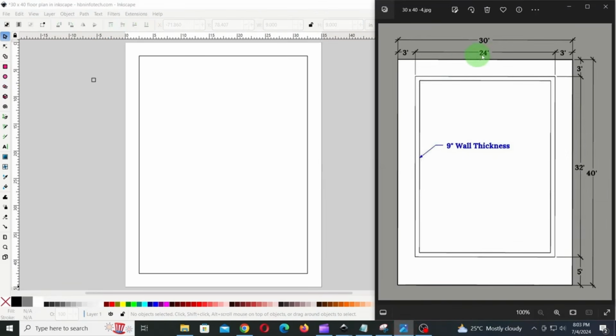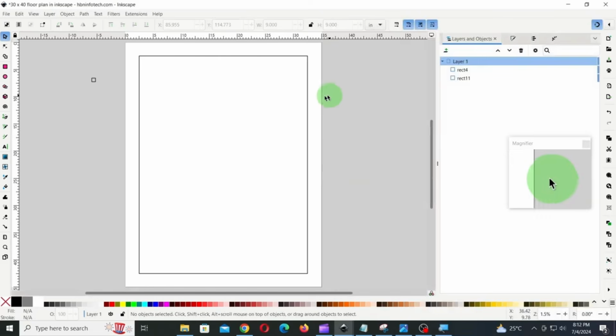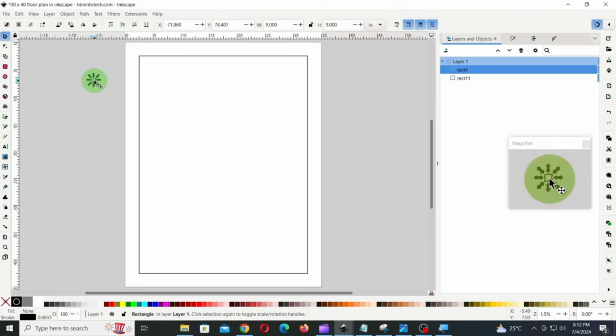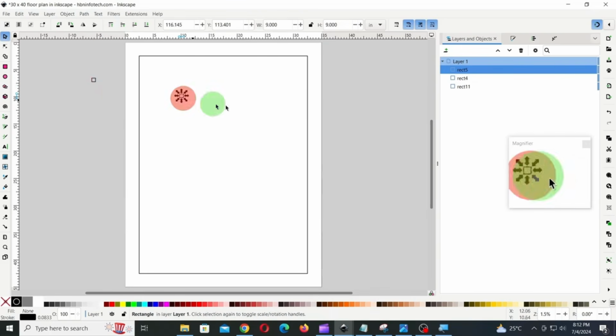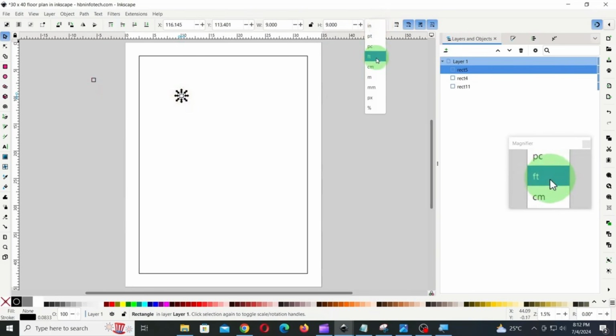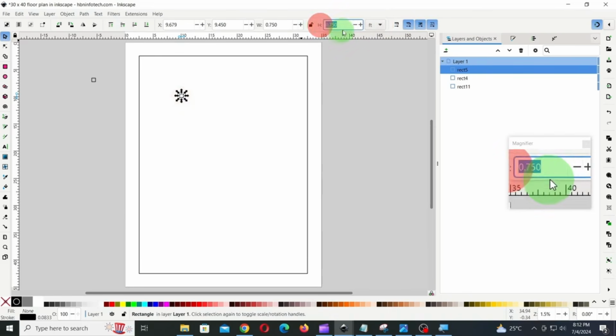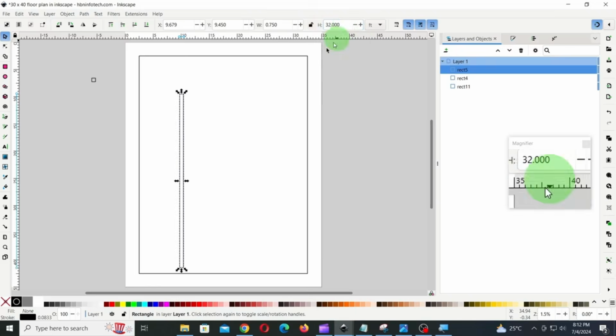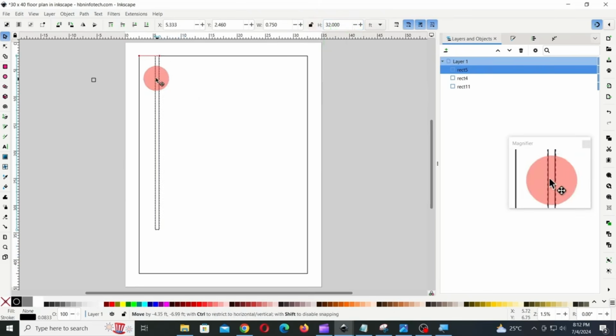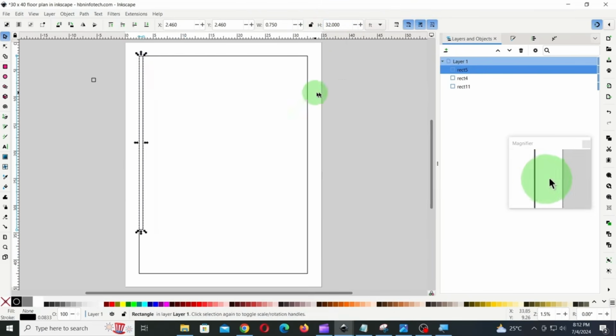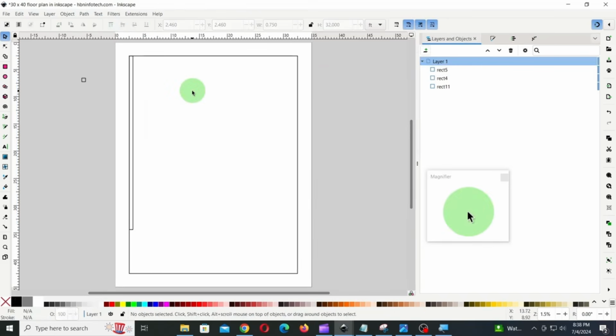The outer wall that we are going to create is 24 feet by 32 feet. So now duplicate the 9-inch square and change the height to 32 foot. Then with the aid of object snap, move it and snap to the left top part of the compound. You might have to switch between inch and feet when required.